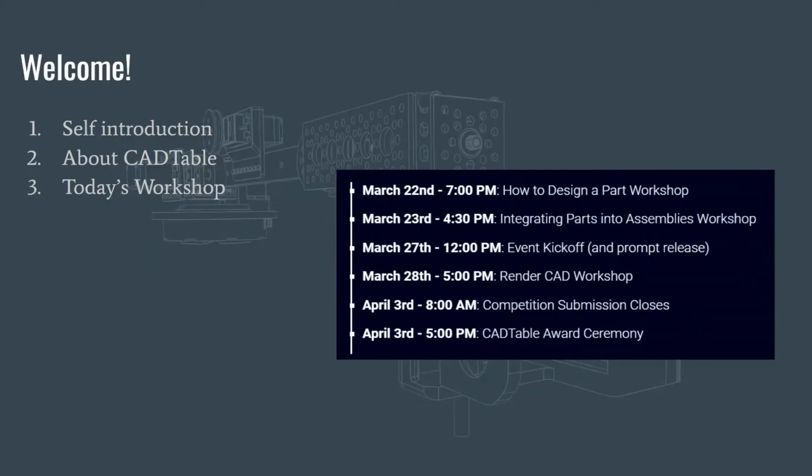So if you change all those appearances in Onshape, it just makes it a lot easier in Fusion. And then in order to get those really nice, amazing renderings that you probably see our team has started to use, that's where Fusion really comes in. You don't have to rebuild your robot, definitely not. We're going to be exporting our Onshape files into a STEP file and then uploading that onto Fusion and doing rendering that way. So with that, I'm going to go ahead and get started.